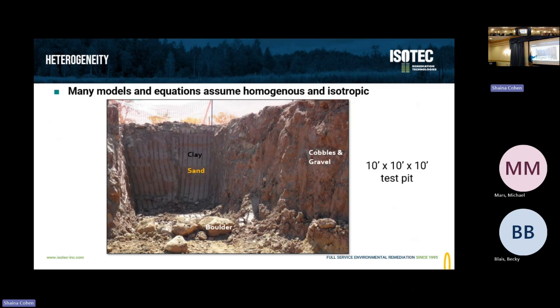And if we were to run a boring here, we can see the clay layers here, and it's a little light here. So if you can take my word on it, you can see the slides, and we have sand below. But if we moved over, this is 3 feet. Now the clay is at different depths. The clay is different thicknesses. There's more clay down here at this level that's not at this level. So there's just variability. If we move over this much, this much, this much, this much.